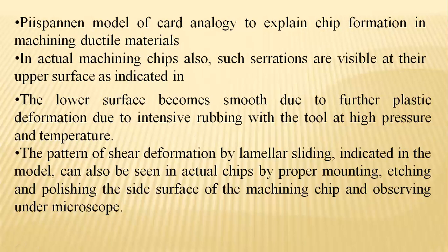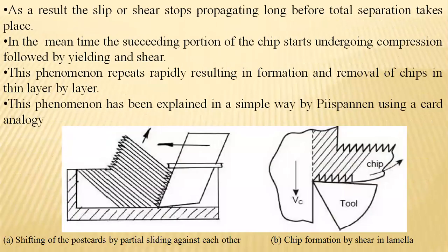When the tool is in contact with the material, as is clear in the diagram, the tool interacts with the material and decreases its diameter, considering cylindrical objects. The material is removed, and at the contact point, frictional resistance or frictional forces create high pressure by the tool, and due to the rupture, thermal stresses are produced, which cause the removal of the material.